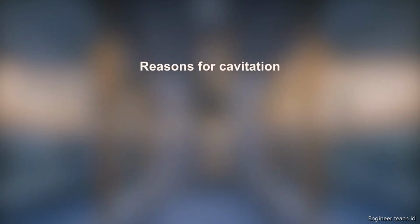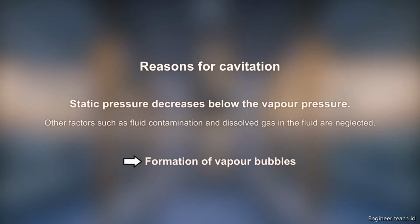This is exactly what happens when cavitation occurs. Bubbles of water vapor form when the pressure in a certain location decreases below the vapor pressure. The vapor condensates back to liquid once the bubble has reached a location with a pressure above the vapor pressure.